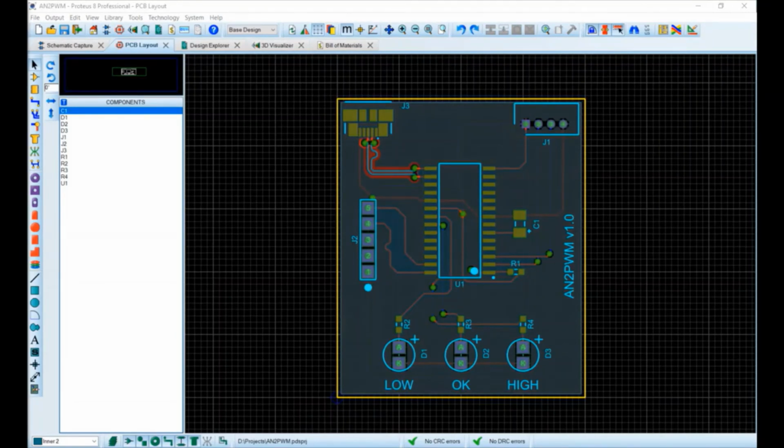Okay, so the last thing we want to do is take a quick look at the project notes module. There's a number of reports in there which can help to make sure that there's no errors on the board, and it's also just a nice way of putting together a sort of an audit of the board / information for the guys doing the manufacturing and the PCB assembly.